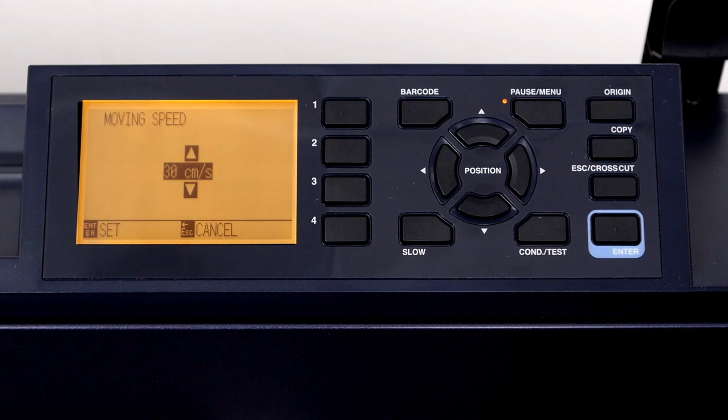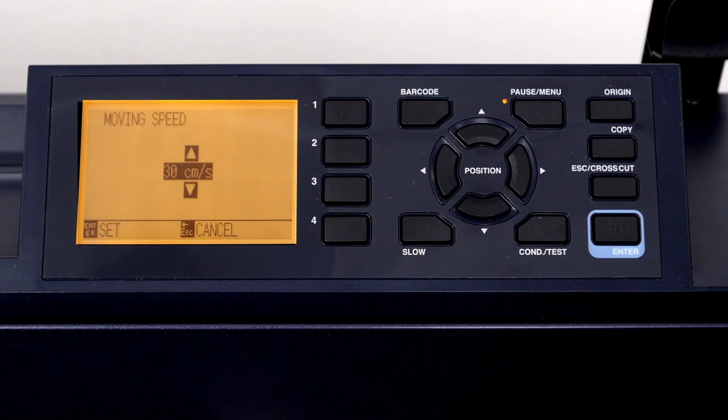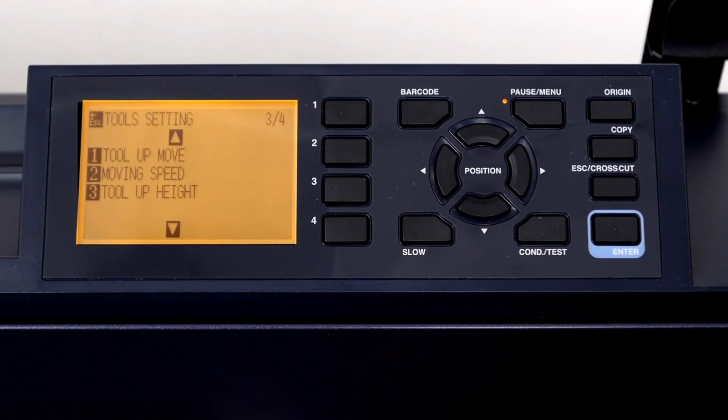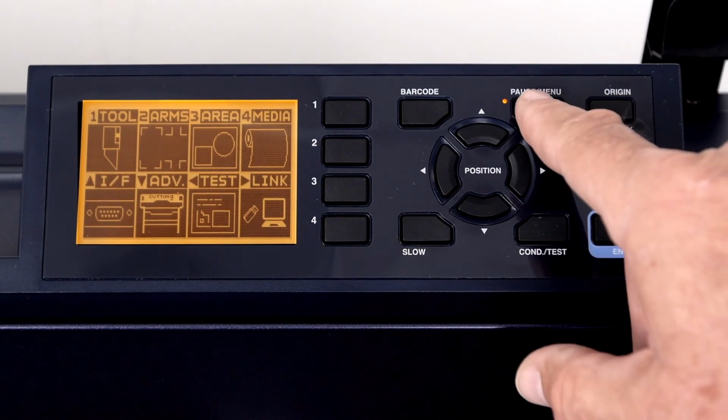In this case, though, we really don't want to change the tool move speed. So to cancel this value or the setting, we can just press the Escape crosscut key as indicated here. And this will bring us back to the previous tool settings menu. Keep in mind that this type of operation is true with many of the menu settings. To get back to the main menu, press the Escape crosscut key again. To return to the default screen, press the Pause menu key.